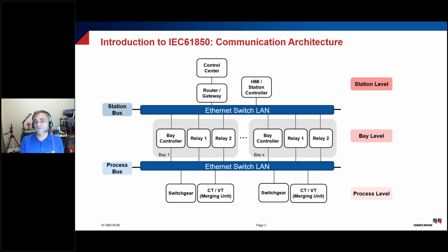So they're the protective relays, and there are also controllers and other devices communicating between these protective relays, and they're at what they call the bay level. These protective relays and controllers communicate up to local HMI screens, or human machine interface screens, pictures of the substation where local control and monitoring can be done. So they call them human machine interfaces or HMIs.